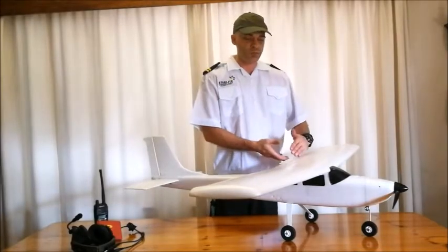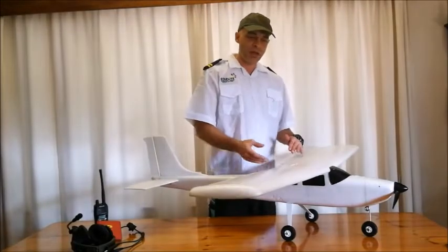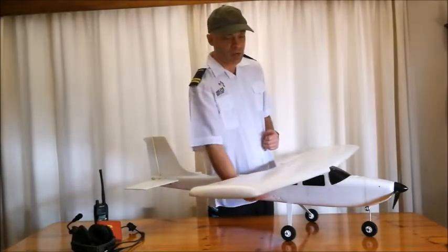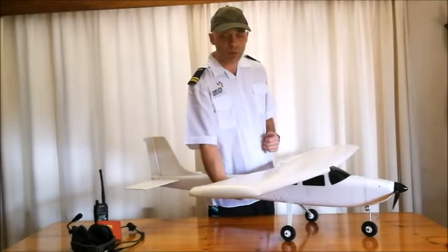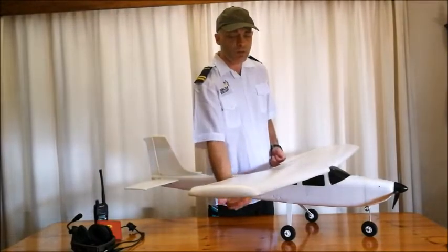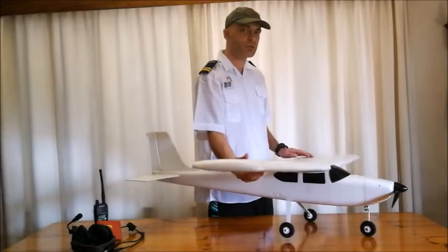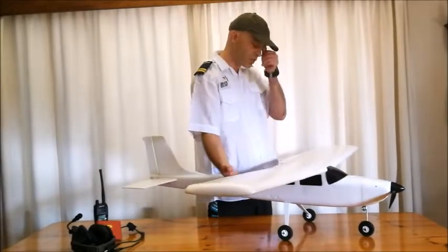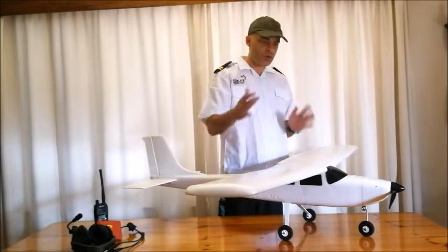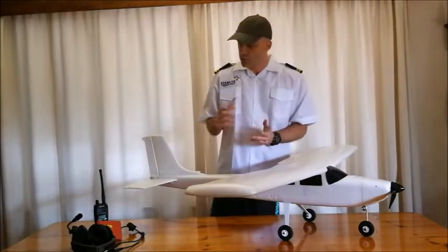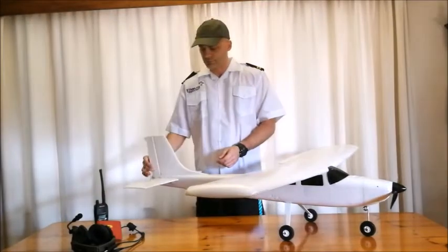So in this case, if this aileron moves upwards and this one moves downwards, the wind is going to hit against this aileron and, using Newton's third law, it's going to essentially push down this wing. Meanwhile, the airflow will come at the bottom of the wing and hit this aileron because it's facing downwards, and that will cause this wing to push upwards. Okay, so that is how your roll motion is able to happen.